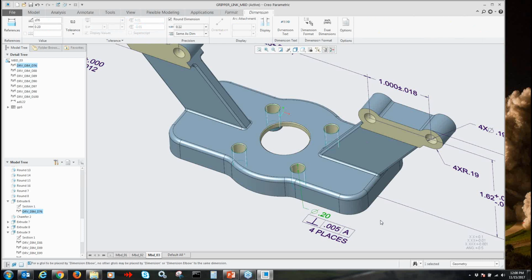So with the capability of sending these out and utilizing our Creo View, when we select on those dimensions or those holes, all 4 holes would highlight for us and show that dimensioning scheme, along with any of the GD&T for it. And again, with the support for AP242, that is a STEP format that now supports annotated models and their ability to gather that information and share that PMI information with your manufacturers or with the end customer. We can then use those STEP files to relay the information the same exact way.